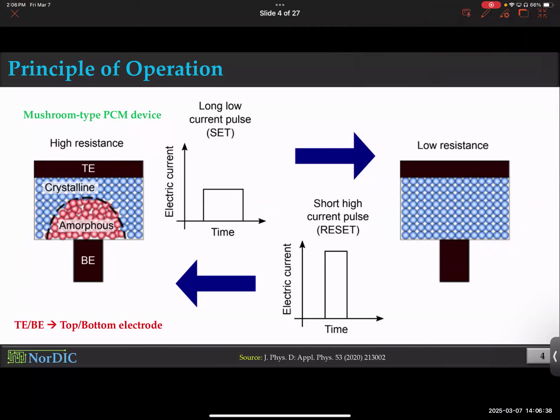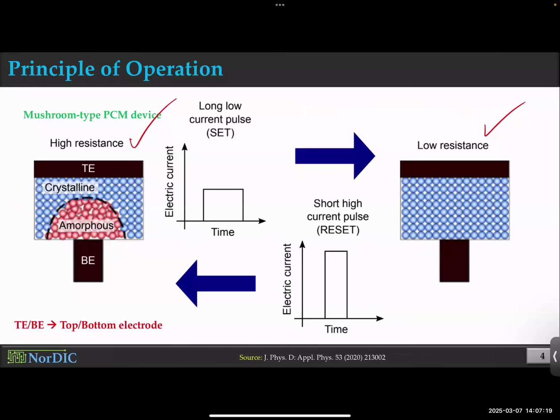Okay. And there are two things that we have to maintain. First, we have to be able to sense it electrically. We cannot just go and see, is it crystalline? Is it amorphous? We cannot visibly do that. We have to do it electrically. And it shouldn't be difficult to do because they give you two resistance levels. You know that already, right? We have gone through this a couple of times already. When you apply a constant voltage to both of them, they will generate different levels of currents. That's how you sense. Super simple, similar to STT-MRAMs as well. And then you have to find a way to program them electrically. But I haven't told you how to switch from crystalline to amorphous. I just told you there is a way. So let's see the way. All right. That comes up in the next slide.